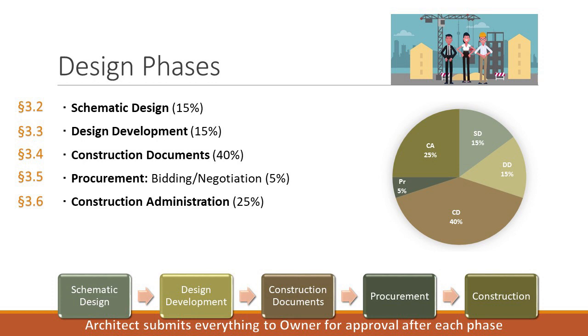But as an overall, schematic design is kind of when you're doing the preliminary stuff, you're setting up the program and everything else. Design development, now you're getting a little more detail. You have plans, you have sections, you have other things. So now the building is being fleshed out. Construction document phase is we've all locked in on what the design is. Now I'm going to actually create the drawings and the specifications from which the building will be built.